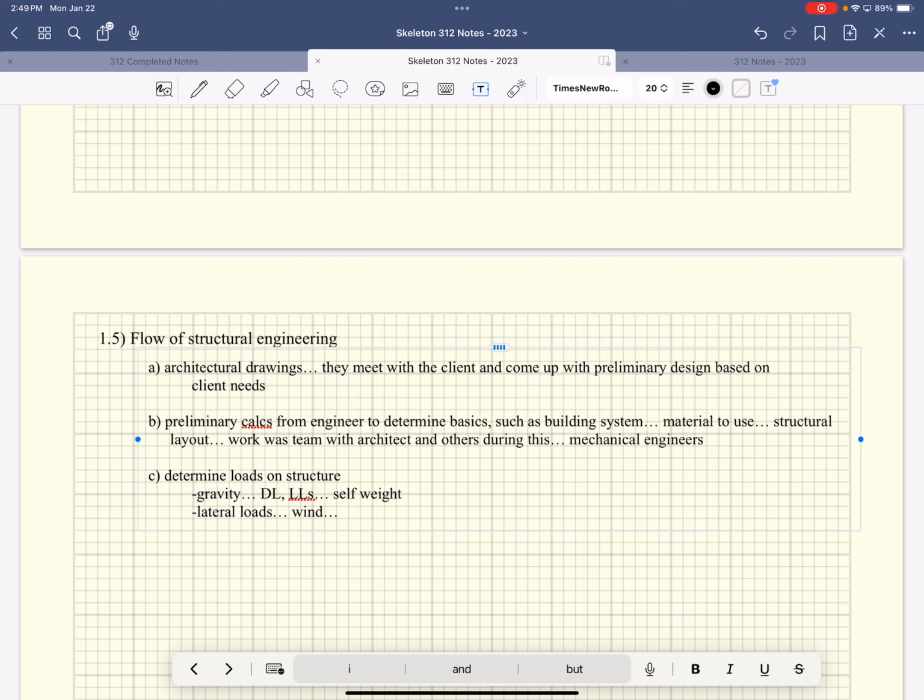It's weird to think about that being a side load. Because what it is, right, is the ground is shaking underneath it, right? It does go up and down some, but it doesn't go up and down as much as it goes side to side. So that's the difference between an S wave and a P wave, right? You learned about this. Did you learn about this? S waves are this. P waves are like pressure waves going back and forth. And so that's where the base of the structure goes.